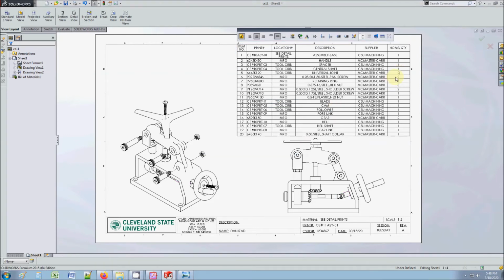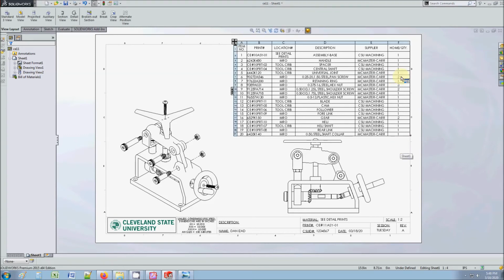So sometimes you have to bypass this. You double click it, break the link, and type in what you want. I don't encourage doing this because now you lose the reference. You lose the link to the actual quantity. But sometimes you have to do that to maintain a realistic bill of material so that when you submit the purchase order, you submit the right amount.